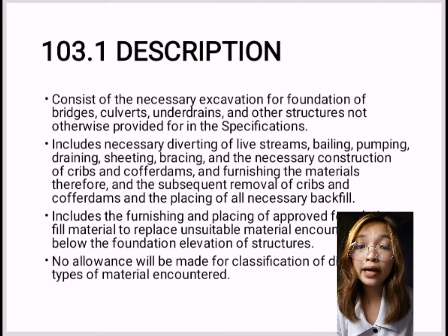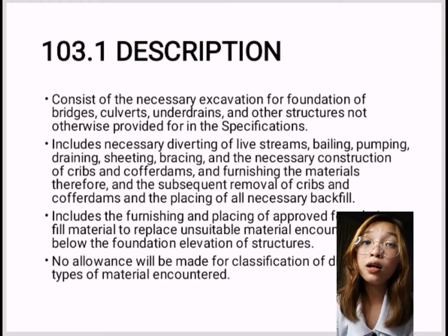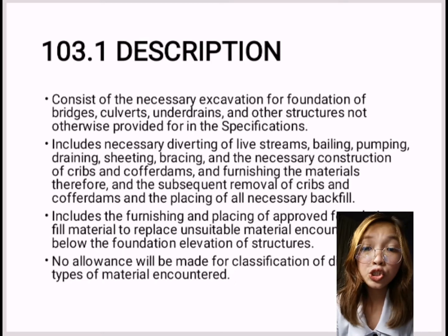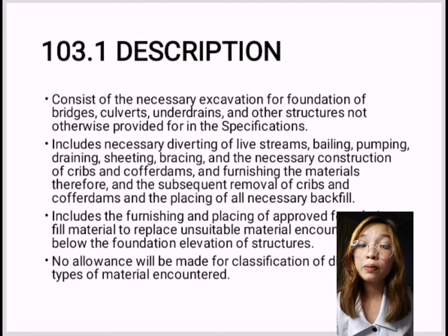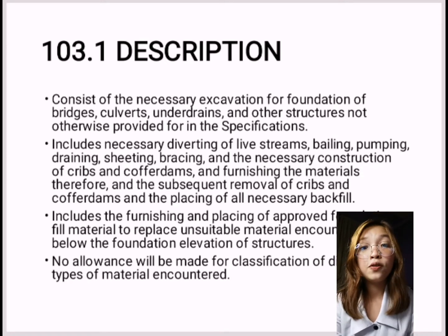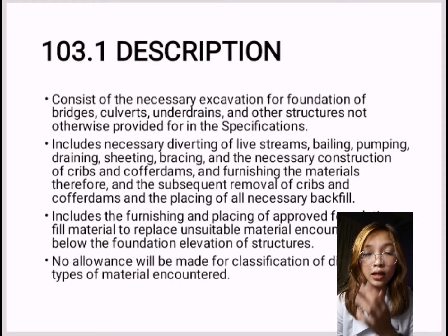These items shall include necessary diverting of live streams, bailing, pumping, draining, sheeting, bracing, and the necessary construction of cribs and cofferdams and furnishing materials therefor, and the subsequent removal of cribs and cofferdams and the placing of all necessary backfill. It shall also include the furnishing and placing of approved foundation fill materials to replace unsuitable material encountered below the foundation elevations of structures. No allowance will be made for classification of different types of materials encountered.